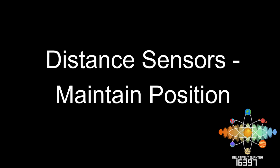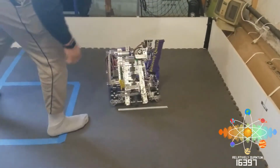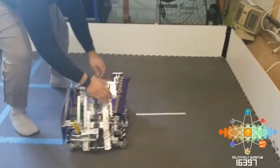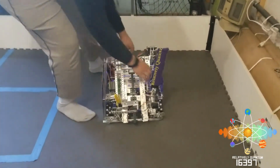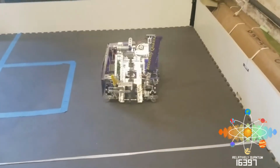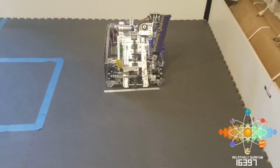Maintaining an angle is important, but so is adapting to your environment. Using sensors that examine the external world is a great way to do this. Thus, we have 2 distance sensors mounted on our robot, one on the side and one on the back. This allows us to dynamically adjust our position depending on environmental variables, such as distances from walls or a wobble goal. In the example visible right now, the robot is utilizing 2 distance sensors to measure the distance to both perpendicular walls and come back to the same position, even when lifted up.